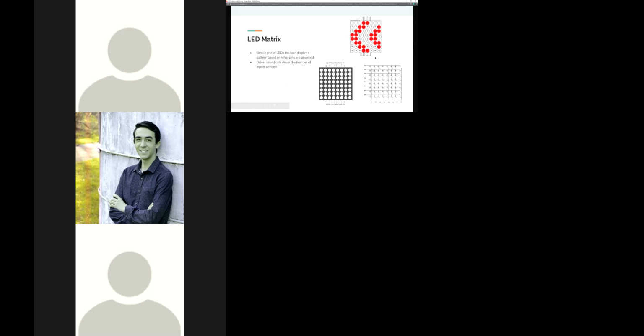We decided to get one with a board on it, specifically because it requires fewer connections from us. Normally, if we use just the LED matrix itself, we need to have 16 cables going each to a different data port in the Arduino. To prevent that and make it a little easier, we got one with a driver board, which only has 5 pins. Basically, it is power, ground, data, chip select, and the clock. That makes everything a lot easier to handle.